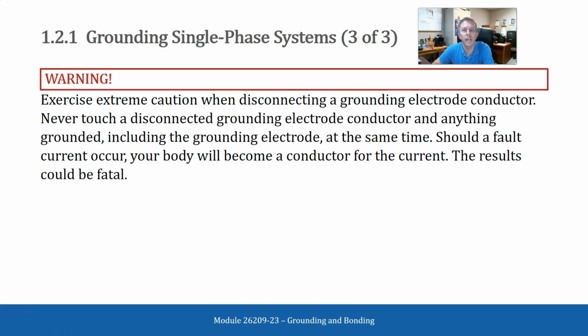Warning: exercise extreme caution when disconnecting a grounding electrode conductor. Never touch a disconnected grounding electrode conductor and anything grounded, including the grounding electrode, at the same time. Should a fault current occur, your body will become a conductor for the current. This result could be fatal.